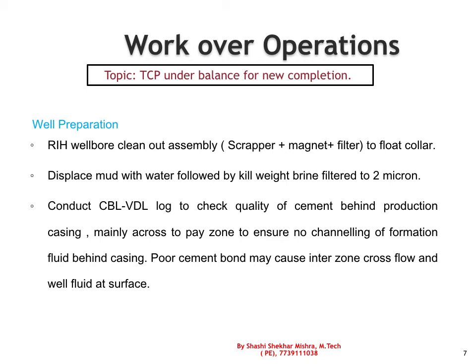Once the wellbore has been cleaned to the bottom, we displace mud with water till we get a good NTU, that is normally less than 30, and once we have clean return water, then we displace the well with kill weight brine, which is also filtered to 2 microns.